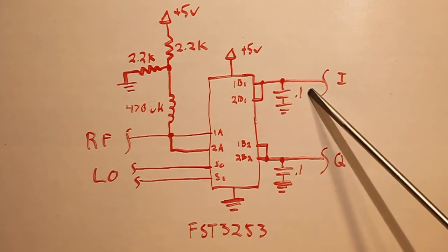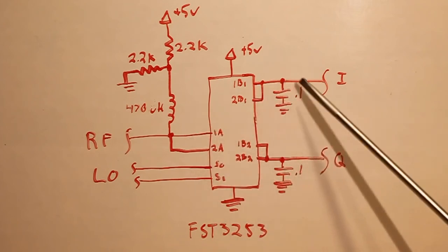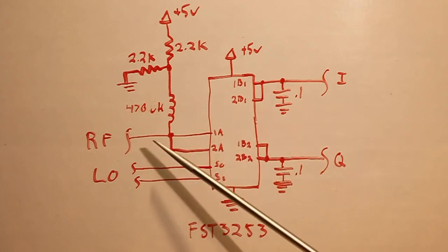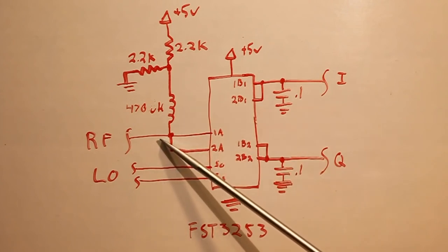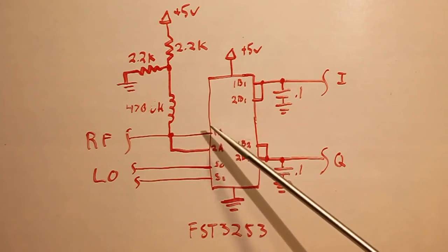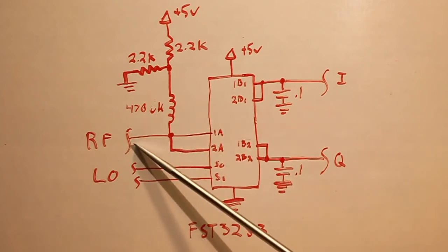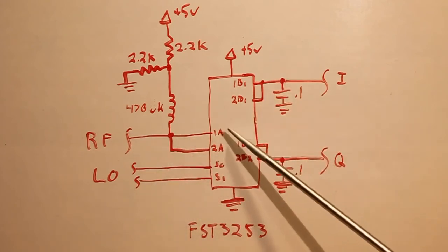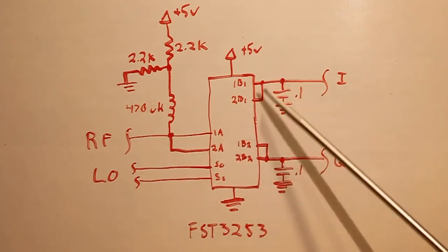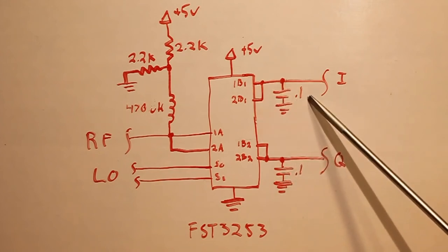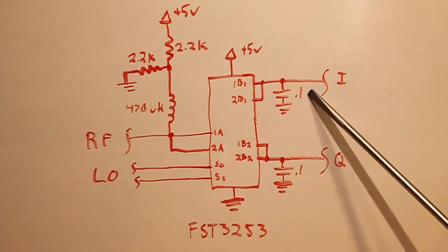Now, it is important to note when you're calculating the cutoff frequency for this low-pass filter that because each output only sees the input 1/4 of the time, it effectively only sees 1/4 of the input resistance. So if you have a 50 ohm input resistance here, the total resistance that this sees would be 50 ohms plus the 2 ohms of resistance here divided by 4, which is 13 ohms. So with a 0.1 µF capacitor here, that gives a cutoff of about 120 kilohertz.